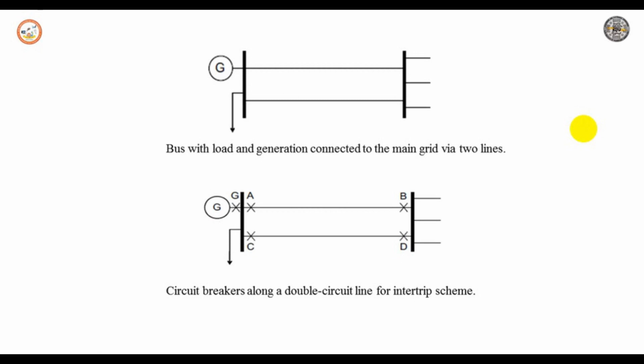is to use a so-called intertrip scheme. The intertrip scheme ensures that when a certain breaker is opened, another breaker will open after it. In the most common application, with distance protection of overhead lines, the breaker further away from the fault is sped up and has to operate immediately. The intertrip scheme for this is shown in the second figure.